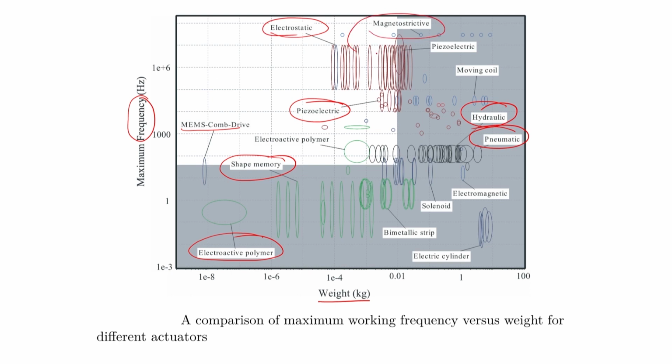So, that is another point. While choosing the actuators, these are the two concerns that you will always find: what is the force versus the weight of the system, and what is the stroke level. So, force and the stroke.